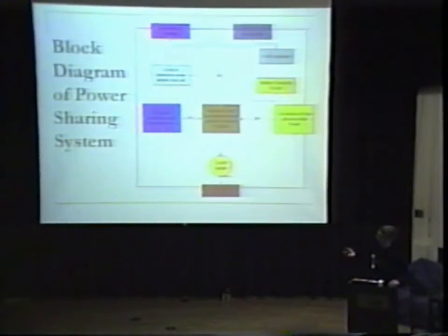And they're all connected to a Schottky diode. So if you had a period of time where there were two voltages going to the same node, the Schottky diode would make sure that there's no damage done to each source. And finally, there's a master on-off switch that would go to the motor.